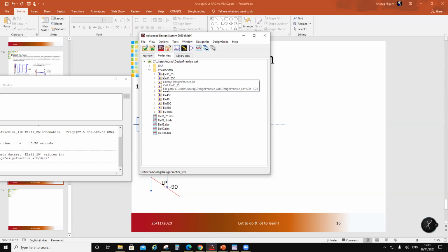So if you read some papers on this, you will know that people don't find any advantage going lower than this phase step. So you will find usually a 5-bit is sufficient for most of your applications. If you go finer than this, the accuracy you achieve will be a diminishing return. So I won't go to 5.625.